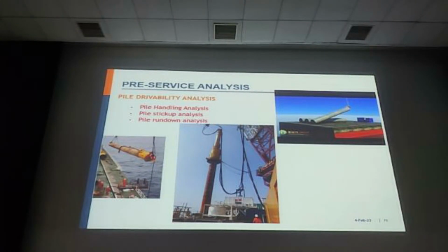So next one is pile. After installing this jacket into that position, then we have to install the pile into that through the length. So for that we have to do pile drivability analysis, whether we are able to drive it. That is a major thing here. Do you have sufficient hammer capacity?